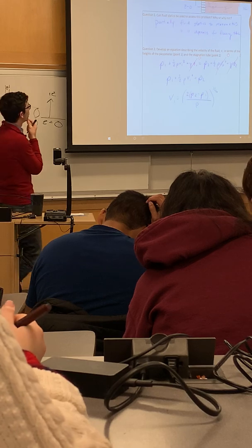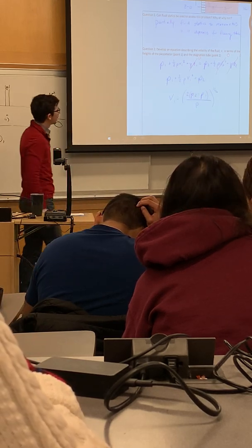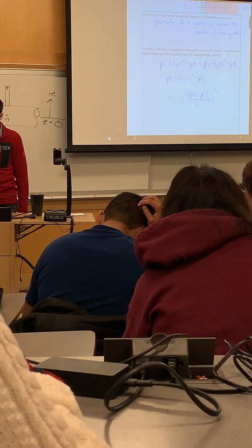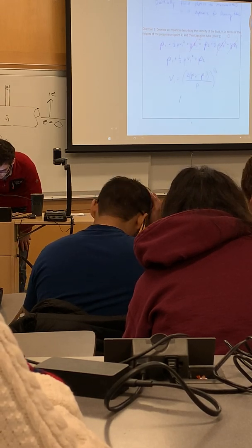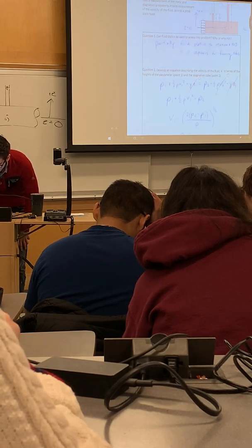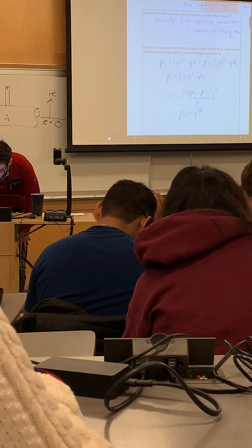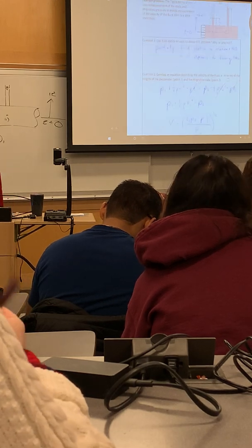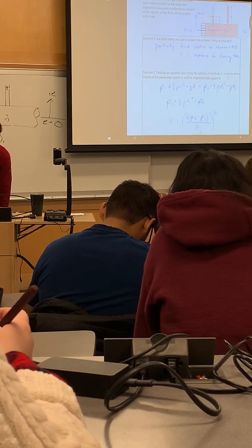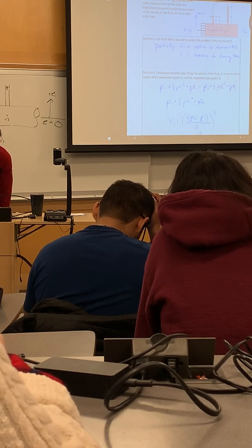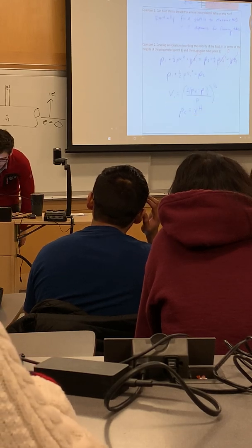V1, which is the velocity at 1. Now the static pressure at P2, right, what's the static pressure at P2? Gamma H, gamma big H, right? This is all a continuous fluid. The specific weight of this pink fluid in the manometer is rising to some elevation H. Right?